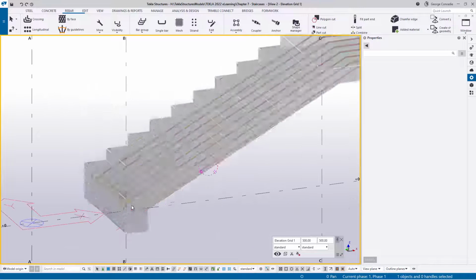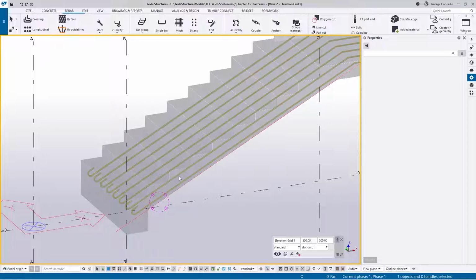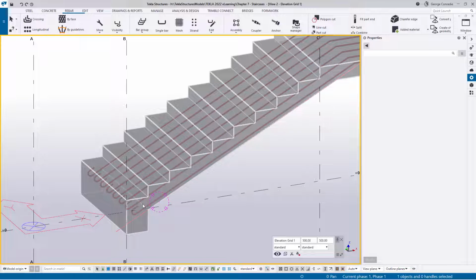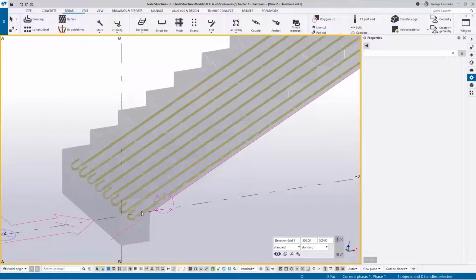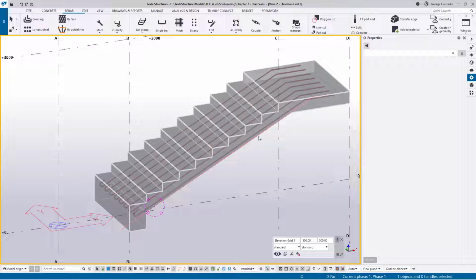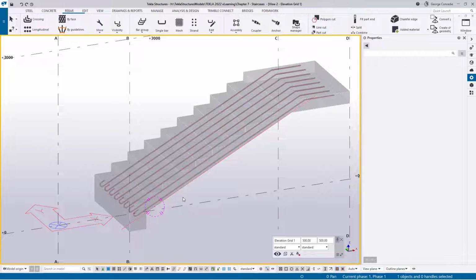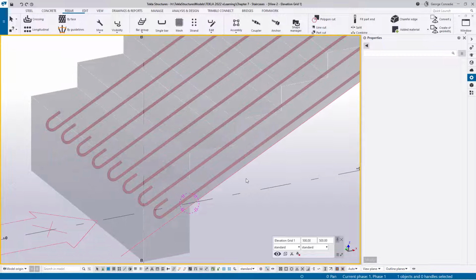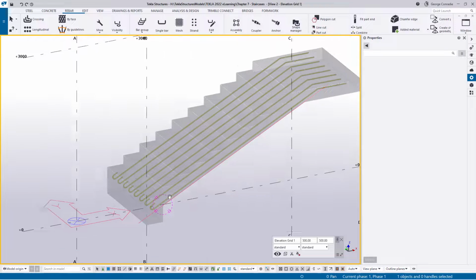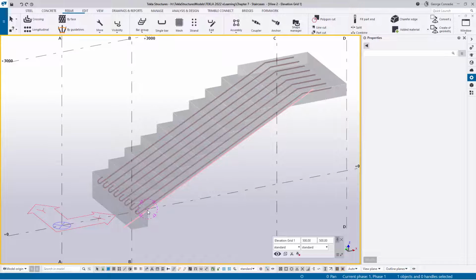The second thing we want to do is these staircases will always, you need to give the guys a bit of room for tolerance. So you have to break up the bars. If you give them one long bar like this, they have to have their formwork spot on, angle spot on, otherwise it doesn't work, and that's not realistic. So what we're going to do is we're going to split this bar twice. We're going to split it here for starters, because they'll probably end up pouring this footing first. So we'll have starters, and then on top there we'll just have like a V-bar that wraps up that top.